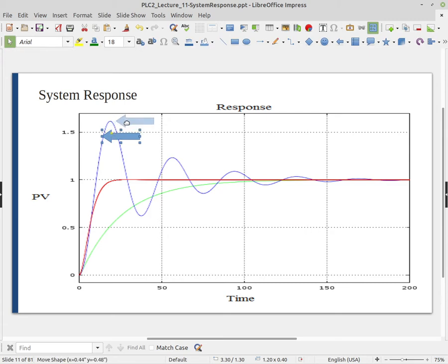That inertia in the system is taking a long time. The control system is now trying to slow it down. Finally, at this point, the control system's got it turned around and is moving back. But then at this point now, that inertia's in there again, and the system is actually driving it too hard, and it now goes back below that value, and it oscillates back and forth before finally disappearing.